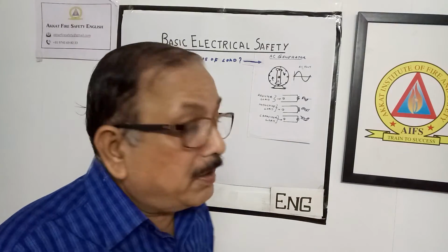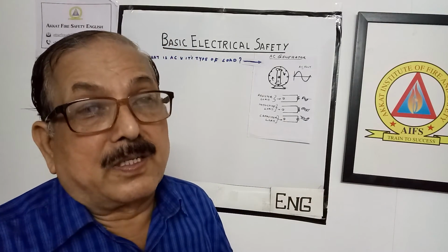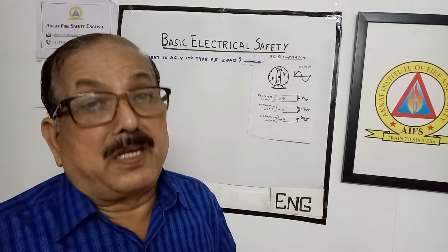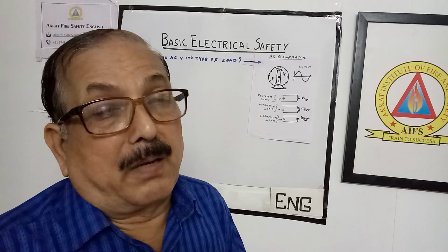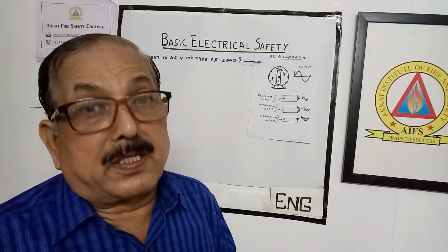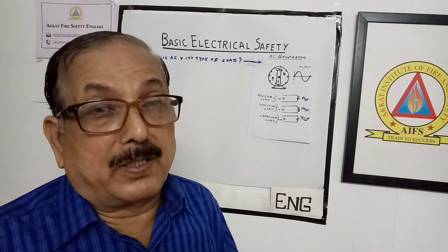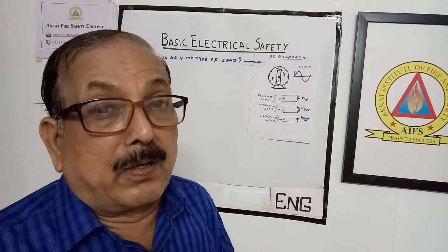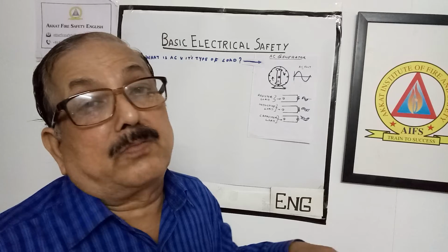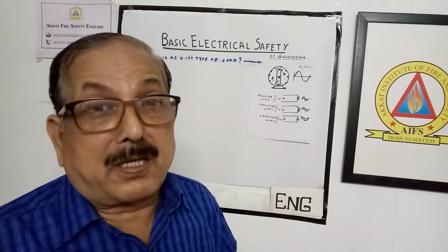But if it's an inductive load, current will always lag. That means first voltage will be coming, then only current will be coming. So there is a phase difference between current and voltage. Similarly, in case of a capacitive load, the voltage will come lagging and the current is coming first.